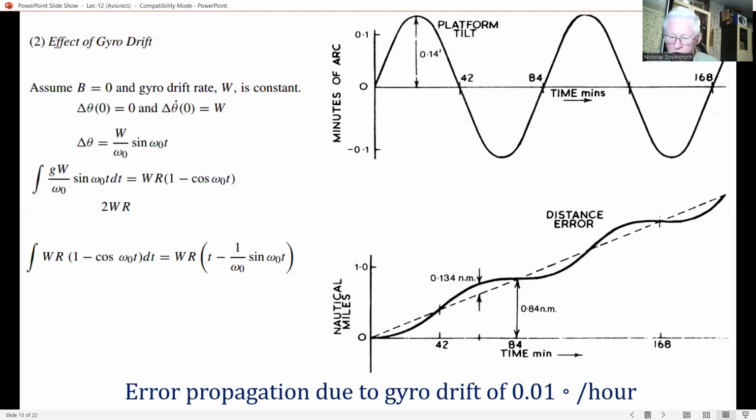The lower limit in terms of gyro and accelerometer accuracies for Schuler tuning to be effective in providing an acceptable vertical reference accuracy in an AHRS is around 0.3 degrees per hour for the gyro drift rate, and 500 micro g for the accelerometer bias uncertainty. This means exactly 2 minutes of arc tilt for the accelerometer bias uncertainty.